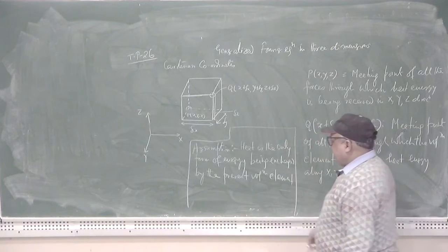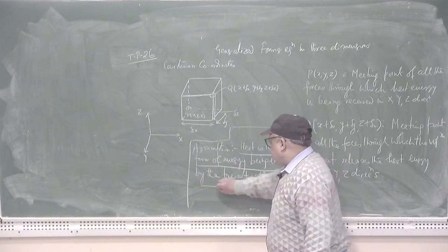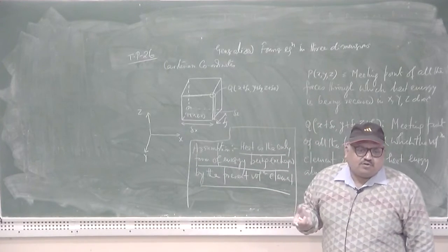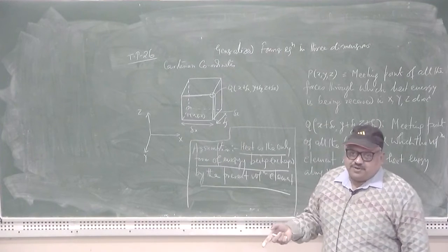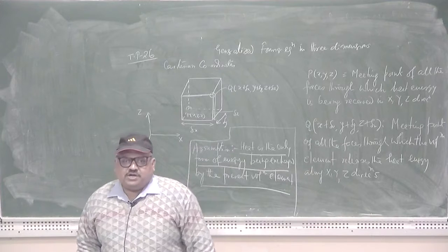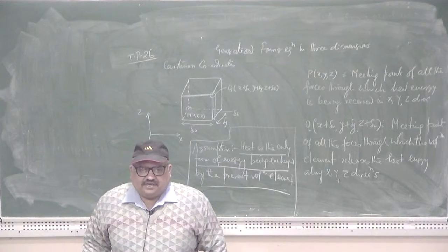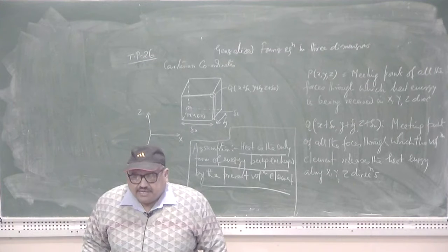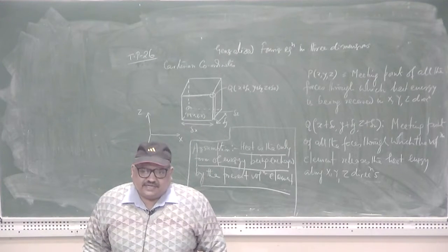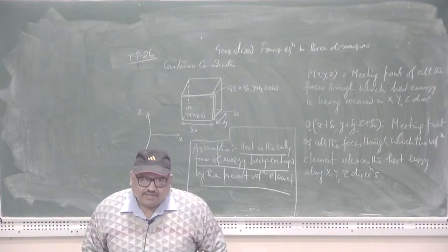Another assumption that we have made: heat is the only form of energy being exchanged by this volume element. That means we need not consider the transformation of heat energy into work or vice versa. So there is no need to utilize the principle of thermodynamics here. The only thing we should utilize here is the conservation of energy, that the entire energy will get conserved during the present formulation.